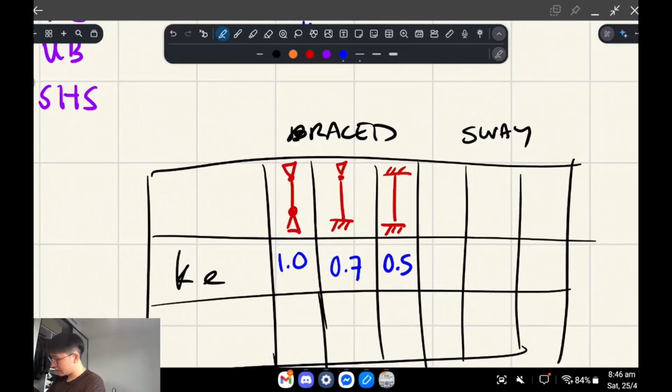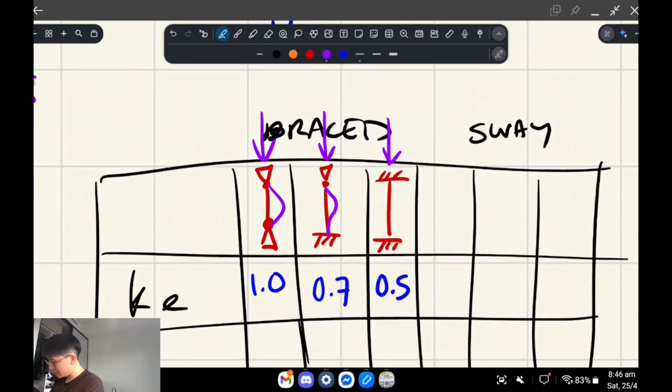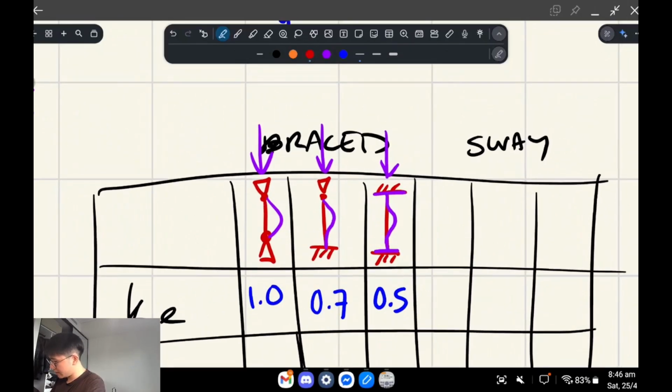The idea is that you're thinking about the length of the C shape caused when we put this into compression. So these are your effective length factors. If this is pinned and the bottom is rigid, the rigid bottom wants to keep this part touching the connection at a 90-degree angle, and the same with here, so the buckled shape has to follow that kind of line.